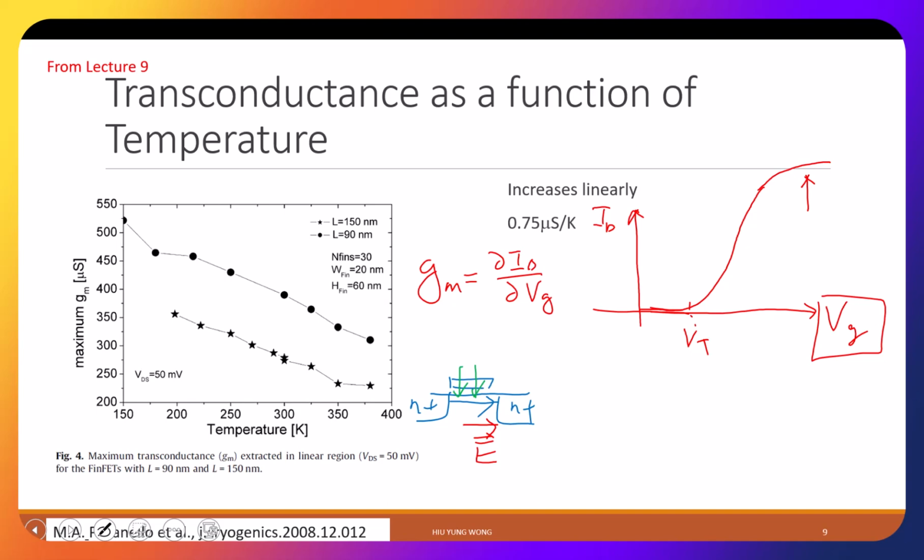So what is the reason? I already gave you a hint: push it against the wall. When you increase VG, what happens? It's hitting the surface. Exactly, right? So you're pushing me against the wall, I get more scattering, right? Because when I run from this side of the classroom to the back, and some of you keep pushing me against the wall, my mobility will reduce. So what type of scattering is this? Surface roughness scattering increases.